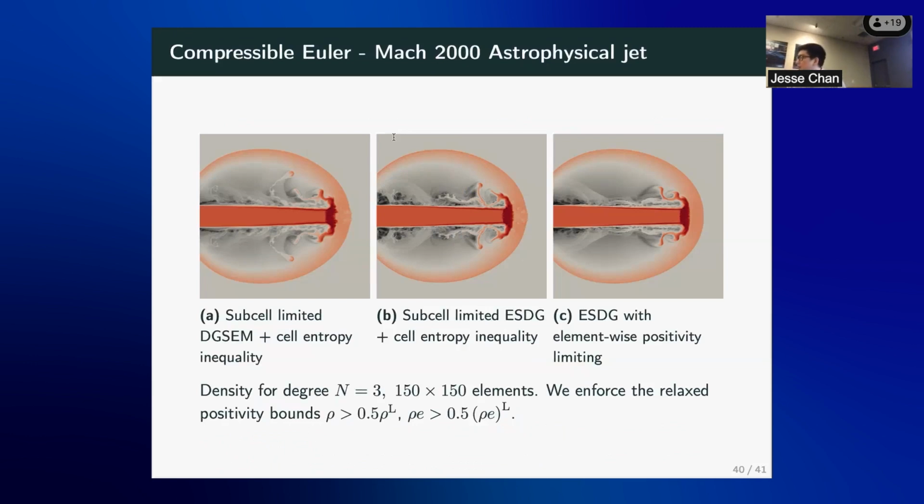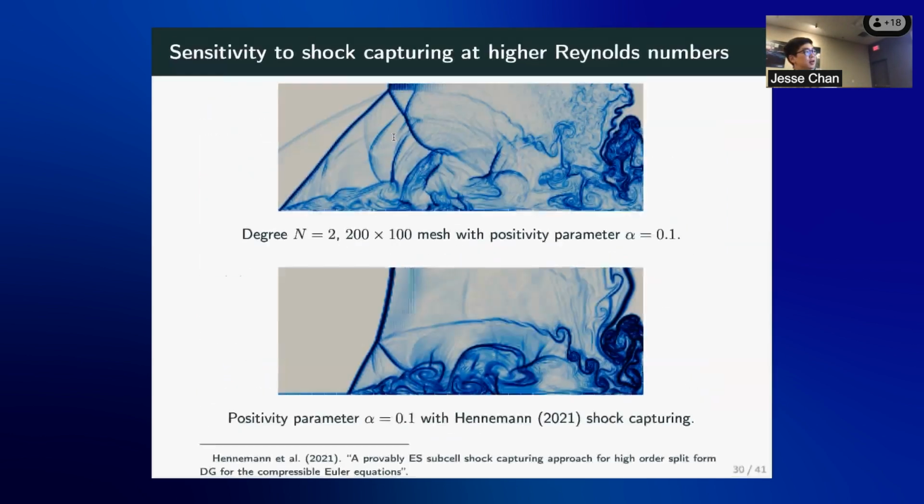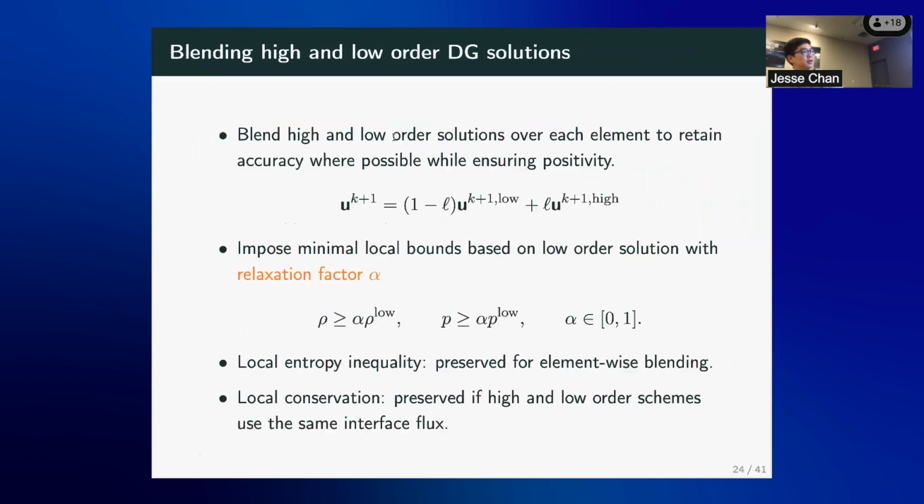You cut out at the back. For the subcell scheme, like when you do the limiting, you put the damping. Yes, you mean the relaxation factor. Is that, like you said that for one, you just use, we actually never tried one, believe it or not. We've only set it to 0.1 and 0.5. 0.1 mostly because we wanted to ensure that we weren't getting clipping or anything. Oh, sorry, like one, but there's one that's just like straight. Yes, exactly. And I guess it would be great accuracy, you'd pick that.